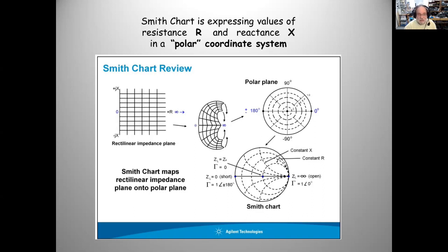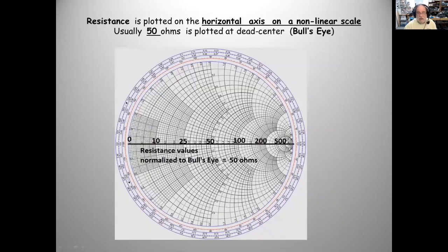Well, it's very clever. The reactance plot moves around so that it gradually curves to the point where you have a polar graph system. Now we're talking about what's in the center and what these different lines and curves represent on a Smith chart. That's what I'm going to take a couple minutes to derive. Fundamentally, this horizontal bar still represents resistance, and I'll show you this in some expanded graphs. As you go up and around, clockwise or counterclockwise, you get reactance. That's the timing issue.